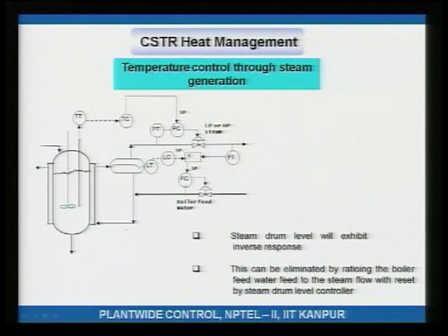And just to describe it to you, what is done here is, this is a tank, a boiler tank, it has got water in it. The water is recirculated in the jacket at a high circulation rate, and because the recirculation rate is high, Tj is constant, the jacket temperature is constant.